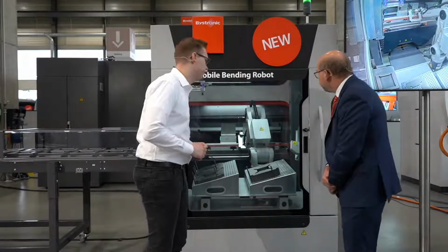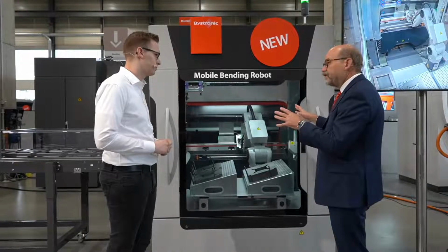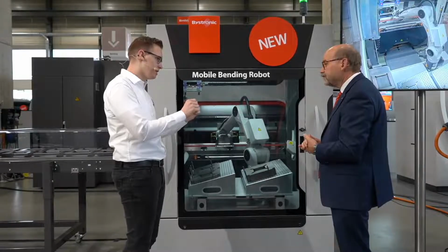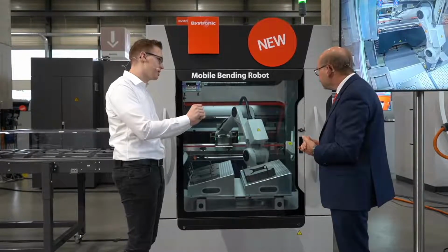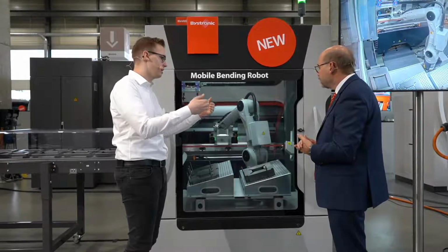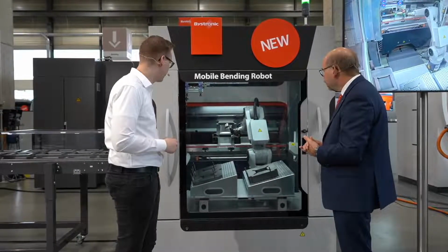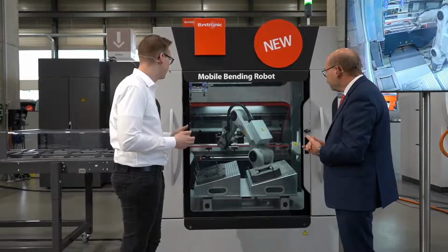And how does the robot know that it touches the back gauge fingers? Because the back gauge fingers have some clicks, and it has to push these clicks. Then it knows, okay, it has the connection with the back gauge fingers, and then we can bend.